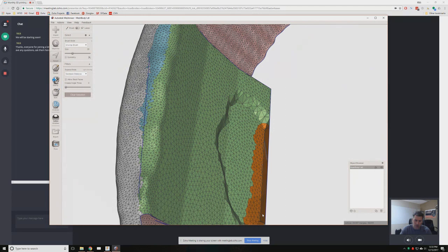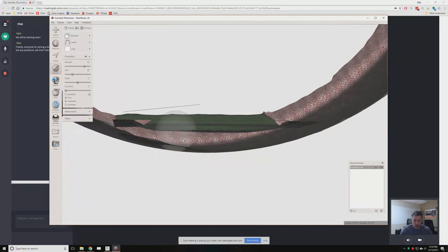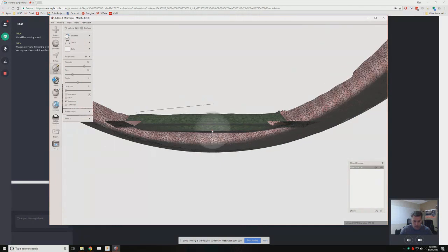And then you would maybe do this again. Another way to do it, maybe with something like this, and Modify or Deform and Warp. I'm not entirely sure if this is going to work. Yeah, maybe. You can only warp that selection, but that brought one part down, and you would match it up with here and then connect it.